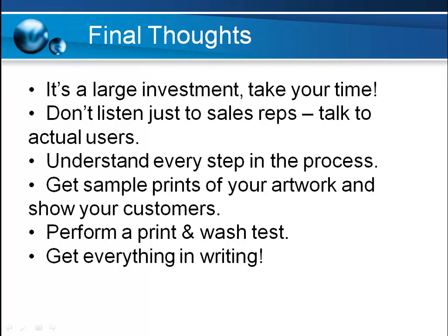I also strongly encourage all DTG users to periodically perform print and wash tests. It's important because that final product is basically your company's reputation. So it might look good when it leaves your shop, but if you didn't perform the pre-treatment or curing process correctly, the minute it's washed, the print quality might degrade. And you wouldn't know that until after it's already left your shop. So that's why I say it's very much your reputation. By performing a periodic print and wash test, you're making sure that all the settings that either you or your employees are using are making the shirts as best as possible.